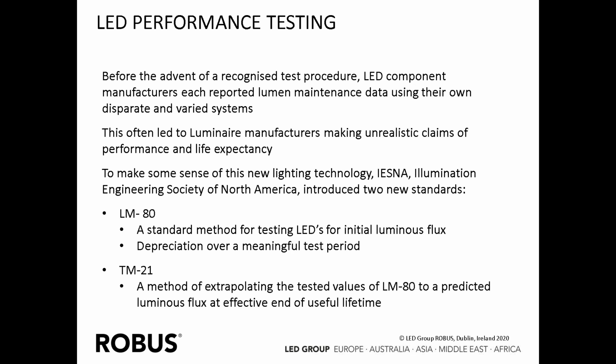IES, that's the Illuminating Engineering Society of North America, introduced two new standards: LM-80, which is a standard method for testing LEDs for initial luminous flux and depreciation over a meaningful test period. They also introduced the standard TM-21, which is a method of extrapolating the testing values of LM-80 for a predicted luminous flux at an effective end of useful lifetime.